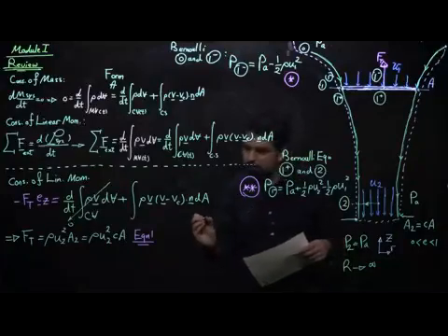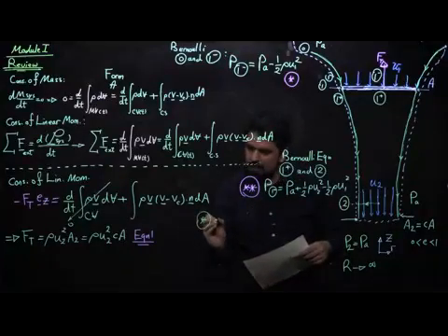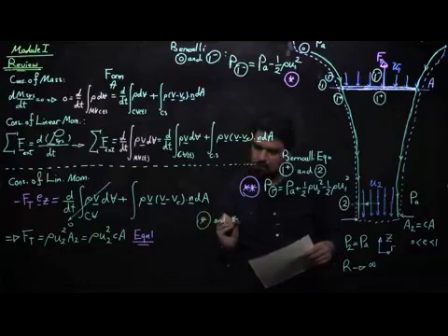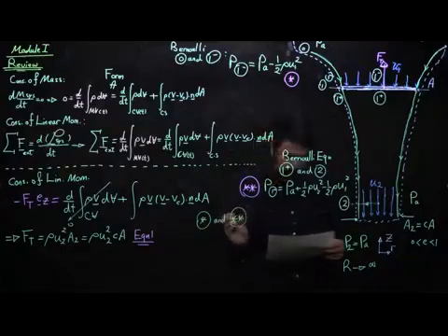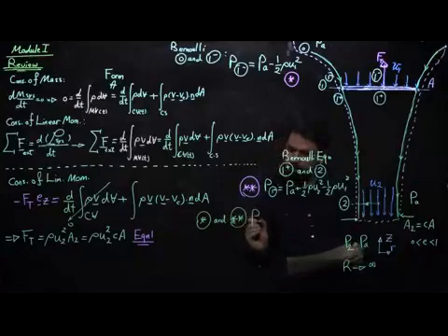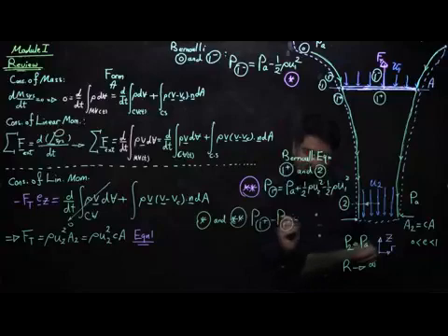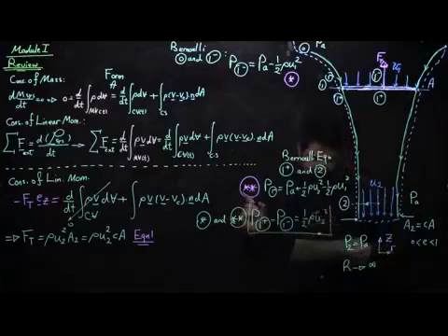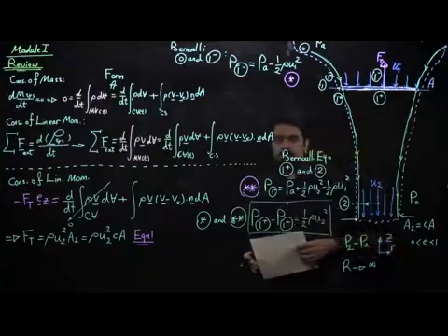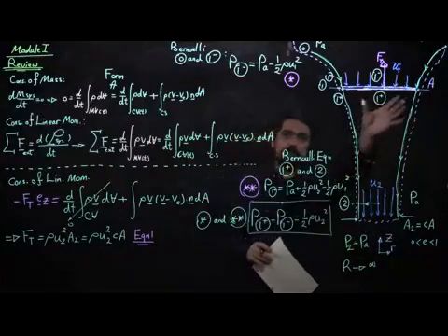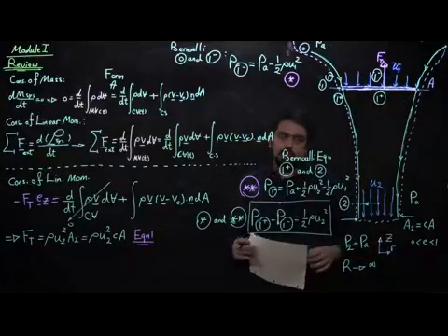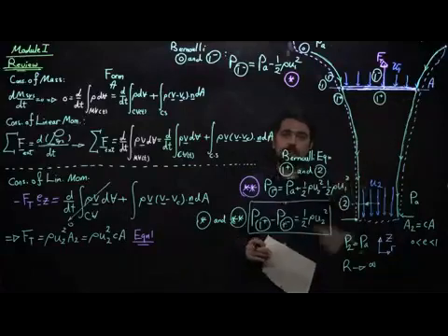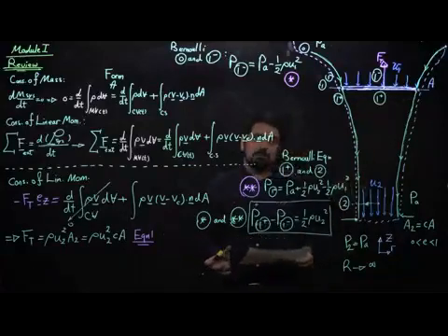So if I combine star and double star, I can easily see that P1 plus is larger than P1 minus, and their difference is half of rho U2 squared. And the higher pressure beneath a blade compared to the lower pressure on the top, the difference between these pressures multiplied by the area of the blade, is what gives the thrust force.